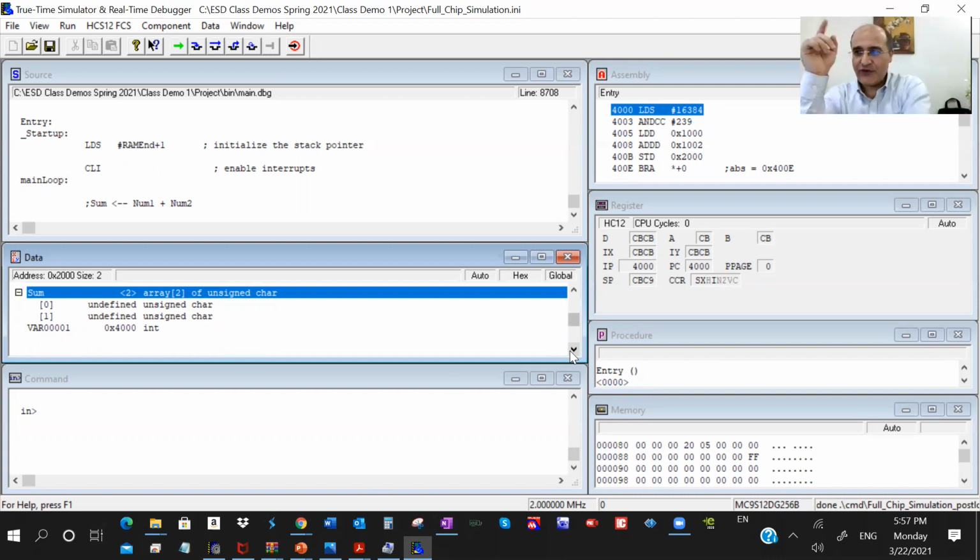Sometimes I forget to initialize something. If it's non-volatile memory, you'll have what you had before. If it's volatile, some assemblers and some compilers initiate the values when they program. But it could be something rubbish, right? If a piece of RAM had power disconnected, it could flush, and zeros and ones are voltage levels. So it is undefined, you don't know.